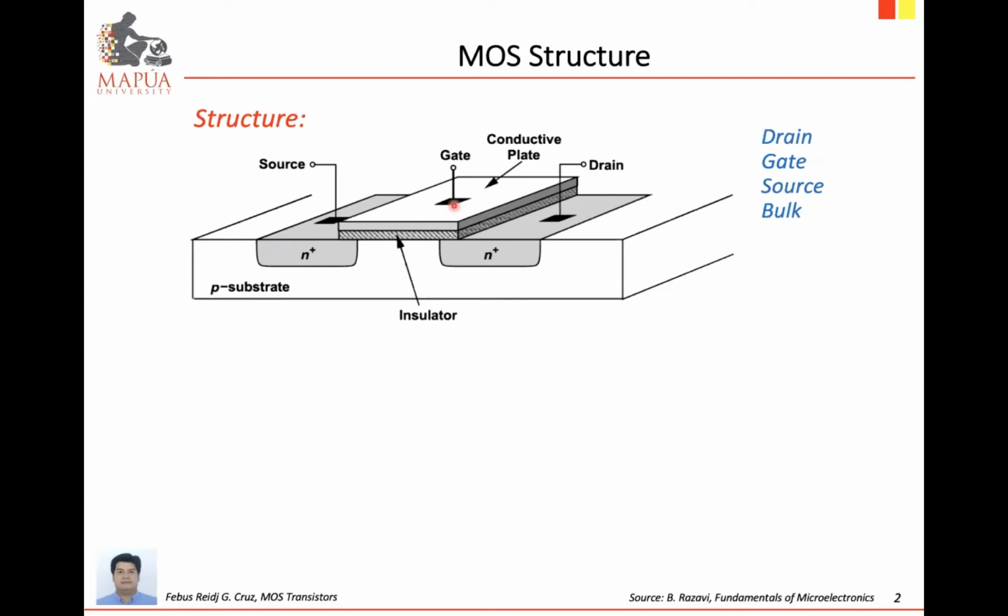Yes, po. All right. Aside from the transistor regions, another important part of the structure is the insulator, the gate oxide layer. It electrically insulates the conductive gate from your semiconductor layers. Another important part is the channel. This is the semiconductor between the drain and source. So the channel is in this portion of the structure, the material between the drain and source region.